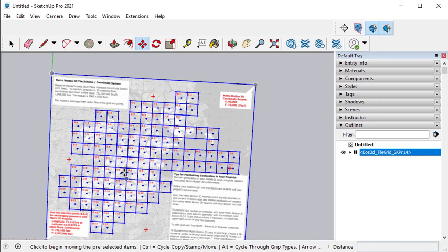So if you try to use a 3D modeling tool when your project is, say, this far from the origin, you'll notice a lot of problems. Things will seem as though they're working okay, and this applies in Rhino, 3D Max, AutoCAD, SketchUp, FormZ, whatever tool you're using. These design tools are intended to be used with an origin that is near or in your project.